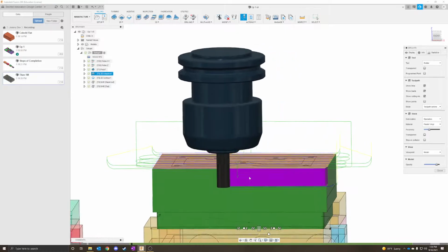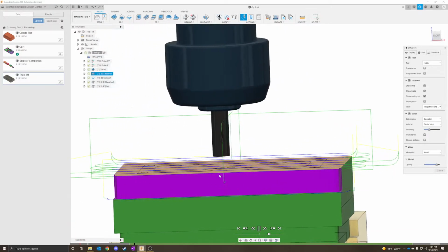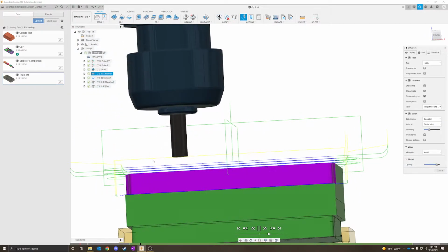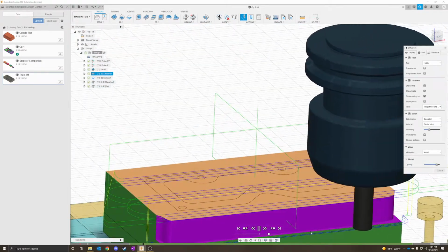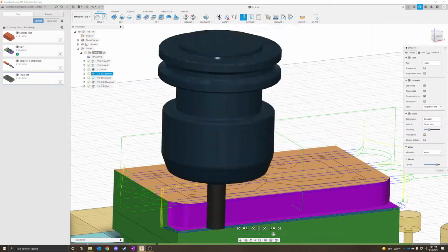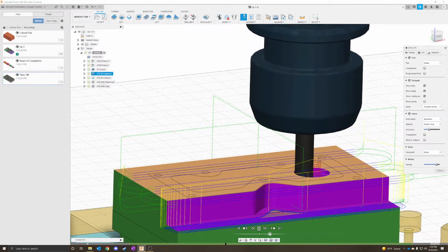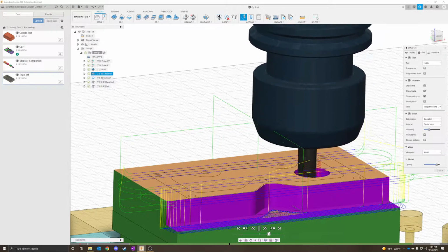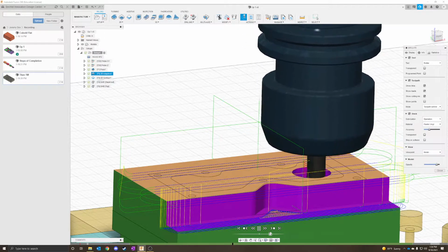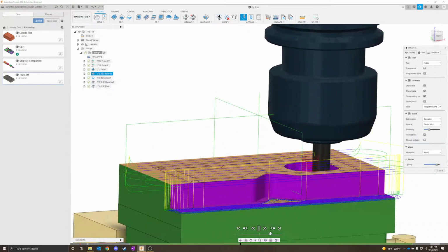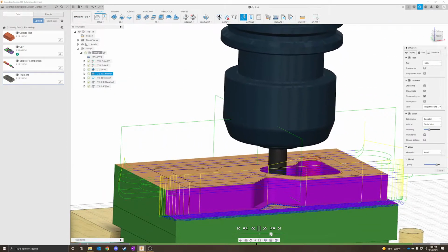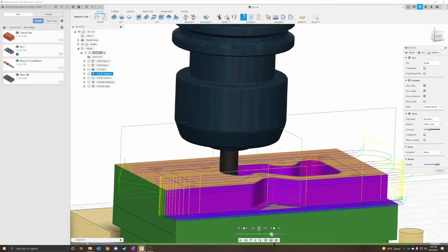Make sure that we're not going too deep with the tool, that we have enough tool to cover everything, right? So we do have enough tool. We're not going to break anything, and that step over is reasonable. There's no collisions. We'll speed it up a bit, and then we'll go inside, right? They're making sure that it's helicing down, not plunging. It's not going to crash. And then it gets to that bottom height and starts to expand outwards to cut out this pocket. And the depth's not too deep. The motions are nice and smooth, no collisions. Everything's good. This is what the TAs are looking for.